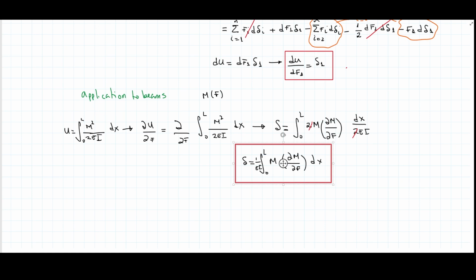And why is this important for us? Well, one of the things is that Castigliano's theorem is very flexible, meaning that it could be applied to linear and nonlinear material. In this case, we're talking about a specific condition, but it's pretty flexible. It could be applied to determinate or indeterminate structures. Determinate structures are those in which the number of constraints is enough to maintain the static condition of the body, structure or element. Indeterminate structures have way more constraints than they need to maintain the static conditions. Castigliano's theorem is being used to optimize structures to ensure that the deflections or displacements are within acceptable limits.